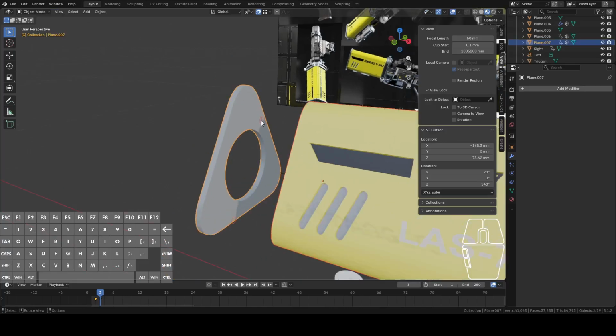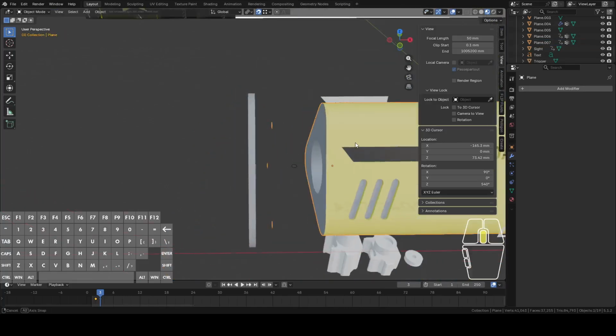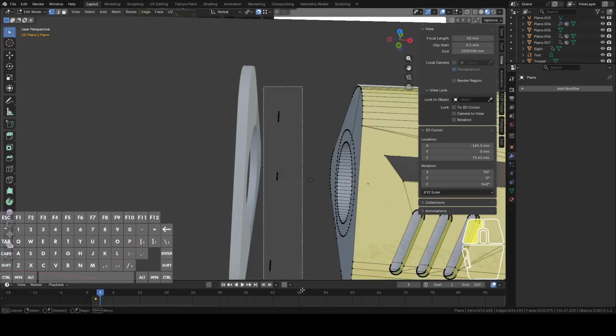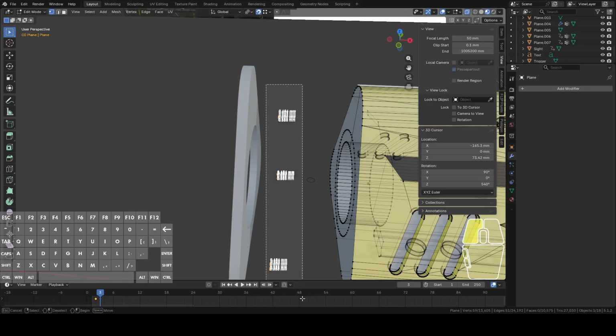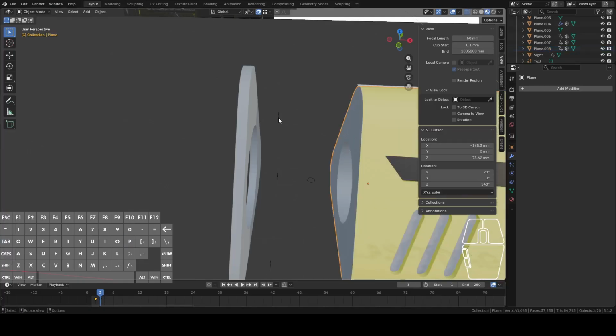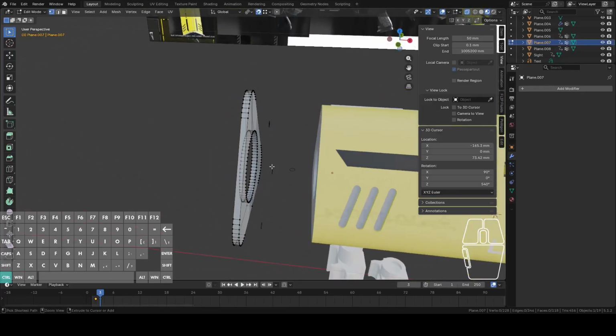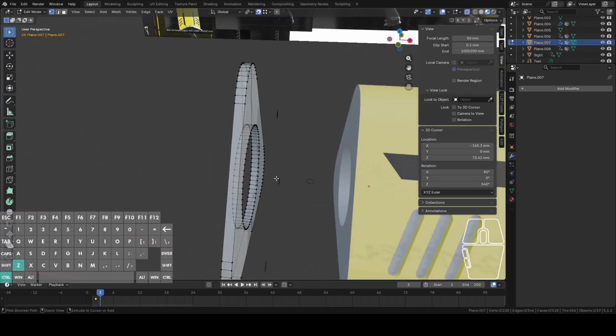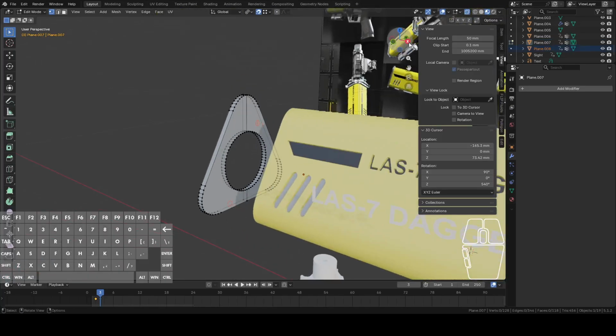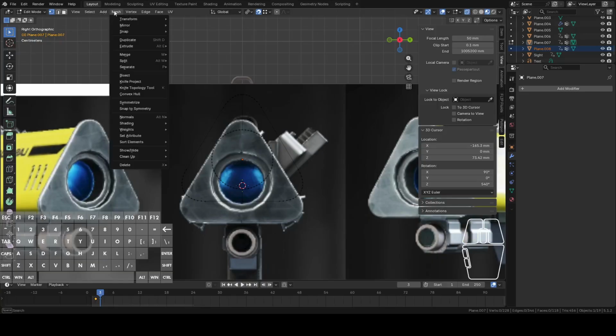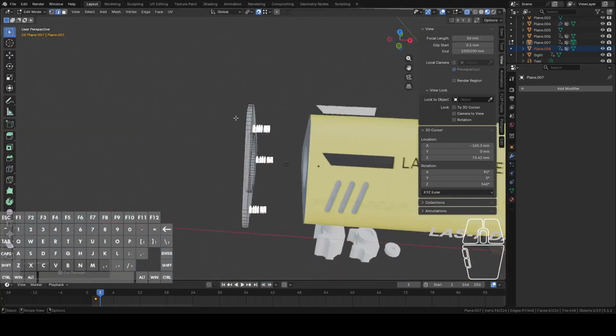Yeah, wait. We still gotta separate these into a selection too. Let's go X-ray. Make sure we got all these pieces. These separate selections, and now they should all be their own things. Good. Alright, let's go into edit mode and try that again. Control, come on, let me get it. Yeah. And let's go back here and try that again. Mesh, knife project, there we go.